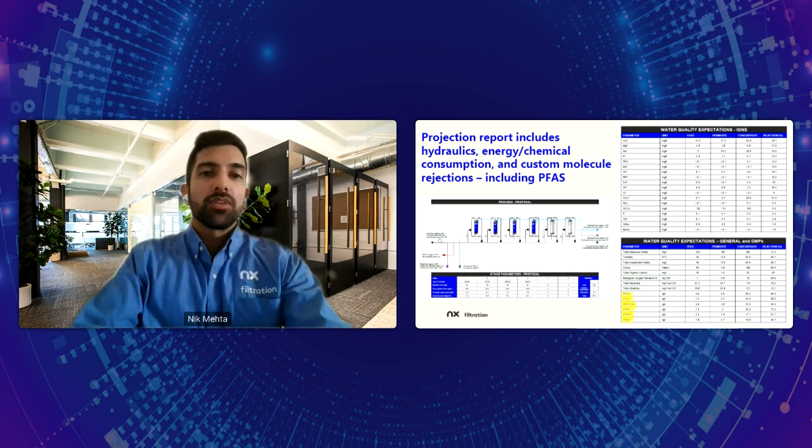It shows these different PFAS molecules and their concentration in the feed and their expected permeate and concentrate concentrations, which is of course going to make it very easy for you to then take that information to whatever other technologies are being used, whether it's on the effluent side, if you need to know what your incoming values are for say your GAC, carbon or your IX, and on your concentrate side, it'll also give you your estimation of your concentrate concentration. Not to mention, it'll also give you your TOC, total suspended solids, turbidity estimations, color estimations